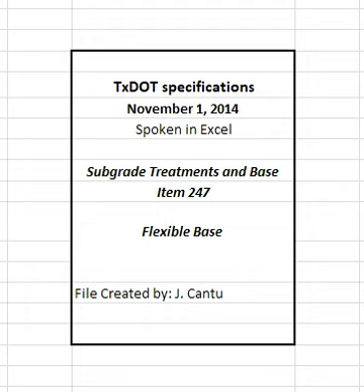2.1 Aggregate. Furnish aggregate of the type and grade shown on the plans and meeting the requirements of Table 1. Each source must meet Table 1 requirements for liquid limit, plasticity index, and wet ball mill for the grade specified. Do not use additives, such as but not limited to lime, cement, or fly ash to modify aggregates to meet the requirements of Table 1 unless shown on the plans.